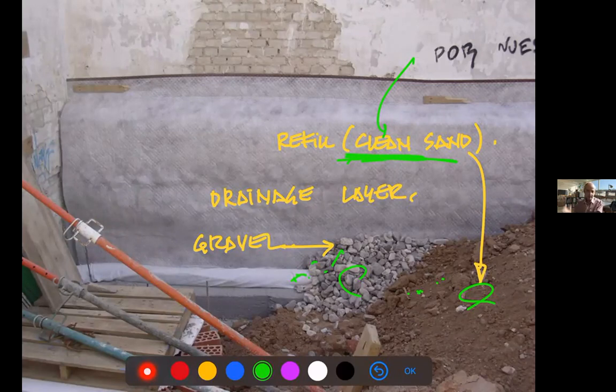So don't do it. And if you're the architect, make sure whoever is in charge of the control, they are using good quality sand, right? Fillings. You can crush concrete, you can crush stones, you can buy sand, and we have, remember, the sand crisis, but you cannot use planting ground, planting only for the top floors, right? The final layers. So careful with this.